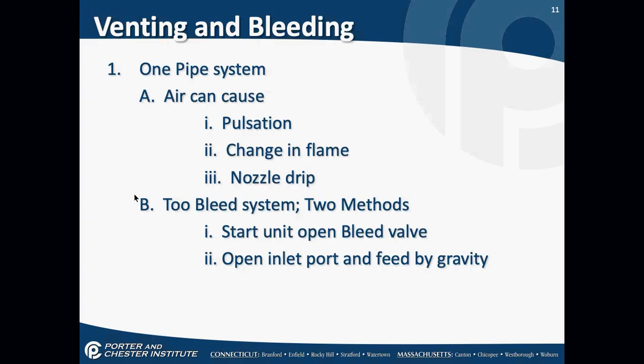So basically, we always have to make sure that there's no air in a system. Anytime you service an oil system where you've opened the oil line, this includes changing a filter, replacing a valve, replacing a nozzle, you absolutely must bleed the oil system to remove all air.